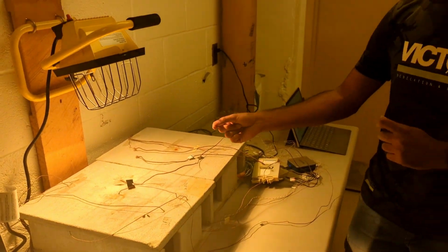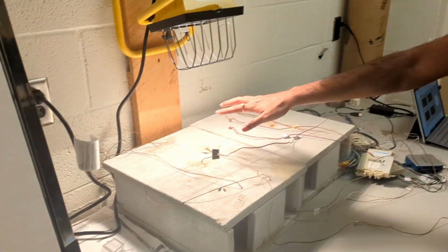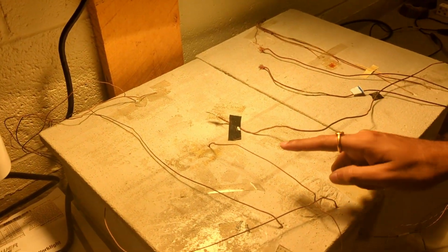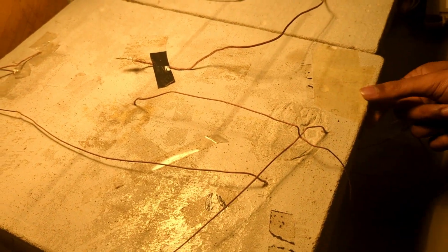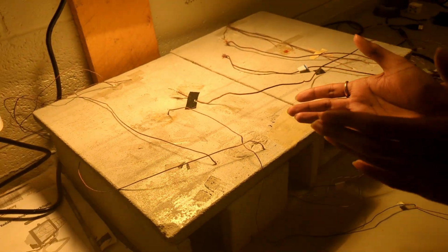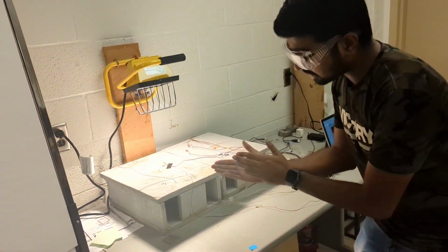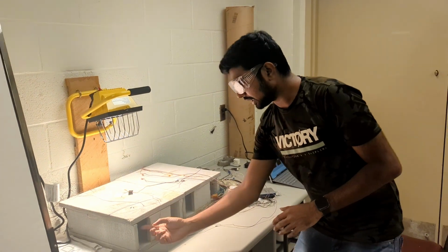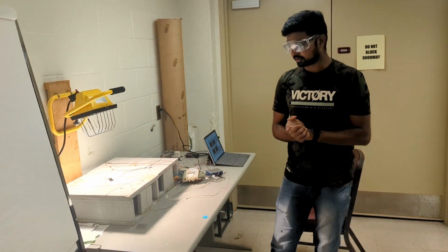As you can see over here, we have this concrete slab which is our experimental workpiece and which is embedded with different thermocouples. So my TC1 over here is measuring the ambient air temperature on the top. My TC2 is this one, which is measuring the top surface temperature of this concrete slab. In the same fashion, I have TC3, which is measuring the slab temperature at the bottom surface, and my TC4 is measuring the ambient air temperature beneath the surface.